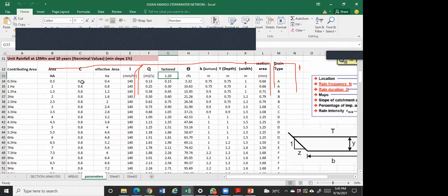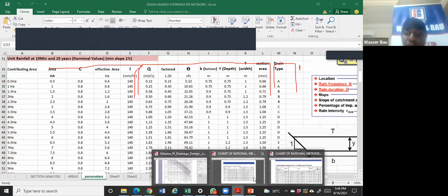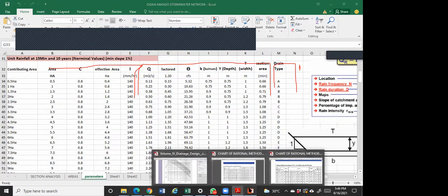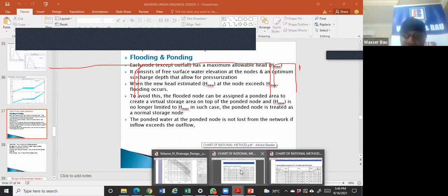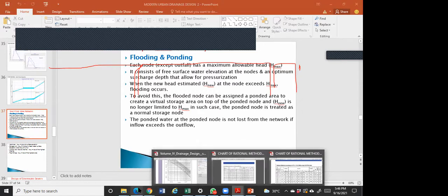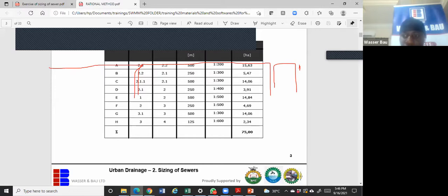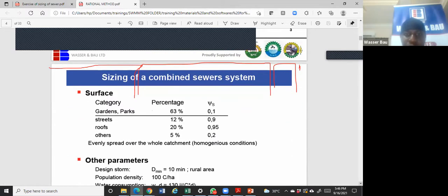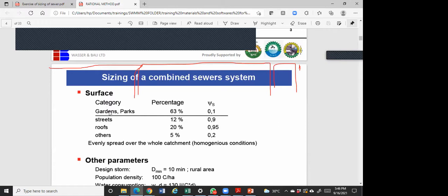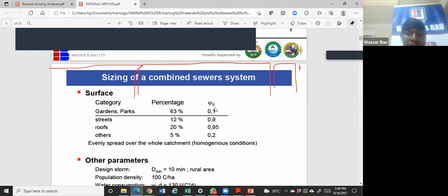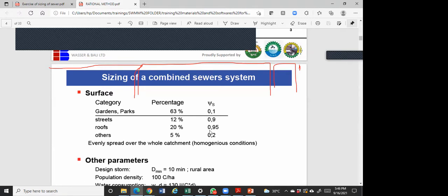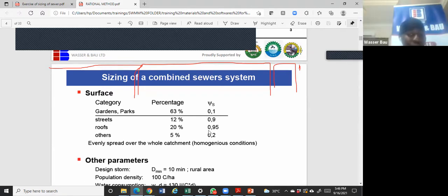Okay. Well, what if you have a heterogeneous catchment where you have to find a composite? If you have heterogeneous catchments, you use the mean weighted average. Yes. That mean weighted average is somewhere. No, it's okay, I have it. It's a good question. If you have a heterogeneous catchment, this is what you do, sir. No problem. You catchmentalize it, you list them irrespective, and use mean weighted average to get the average that you now use. Okay. So for any particular catchment, you use different